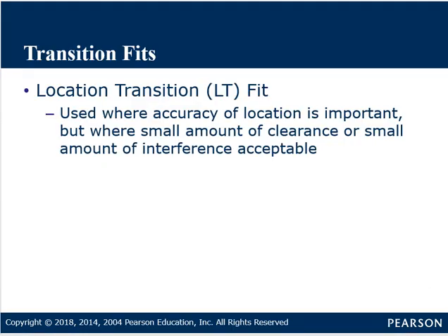And then we have transition fits. That's where accuracy of location is important, but you really don't care if there's a little bit of clearance or a little bit of interference. That's where you would use a transition fit.